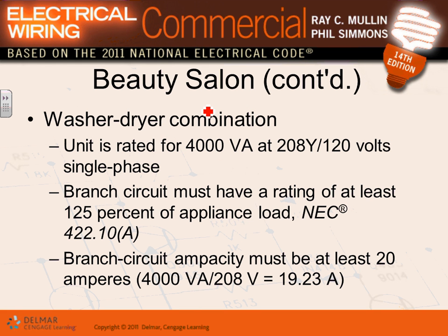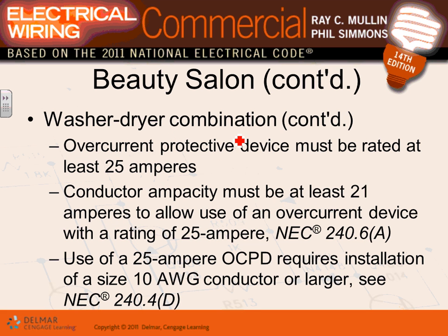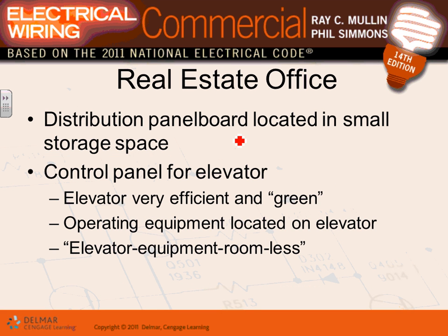circuit breaker. Here's a washer and dryer, guys. They have a washer and dryer that happen to be single phase rated for this. When you do your calculation, the same thing: you take the volt-amps divided by the voltage, multiply by 1.25 and size your equipment. This is just going through a couple of loads that they have. So in a case like this, that will be a 25 amp circuit with number 10 conductor feeding it.